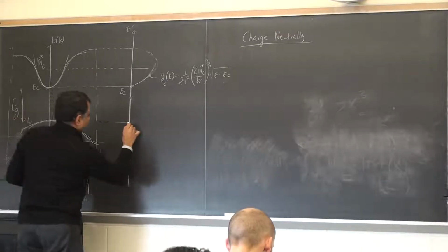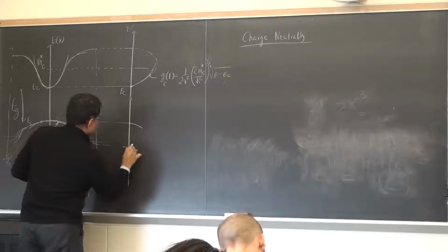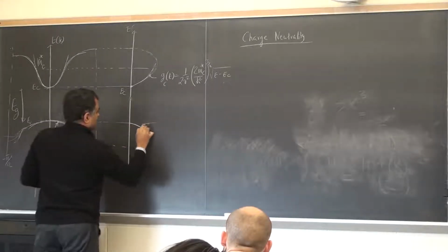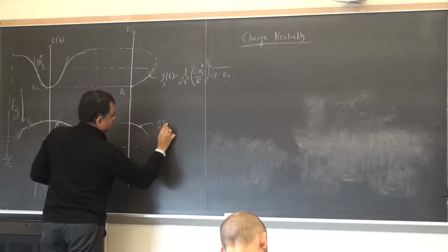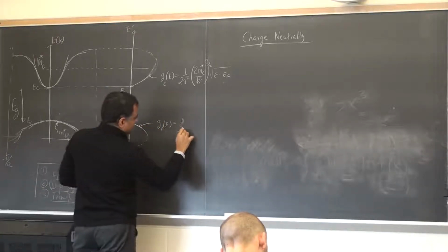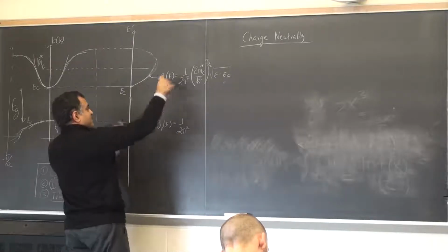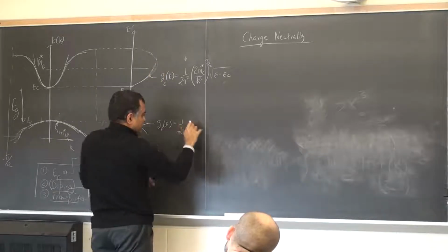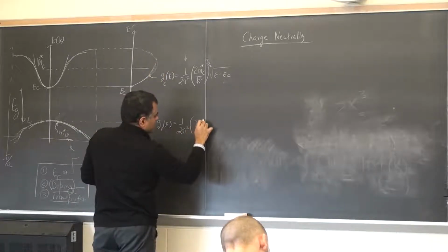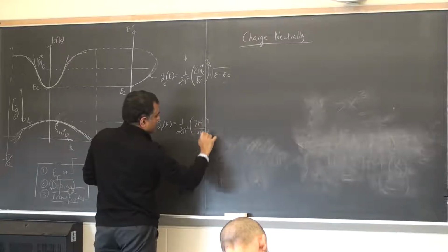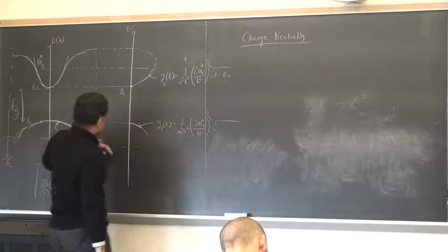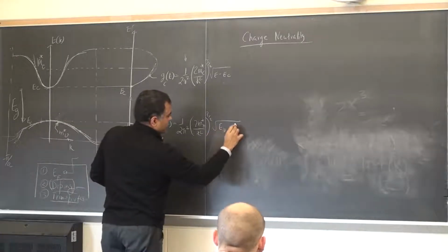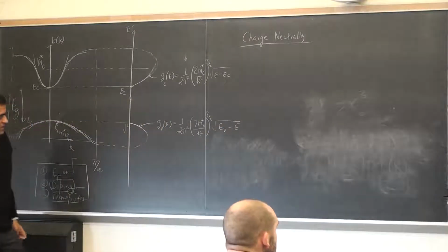And exactly in the same way, the valence band will also increase as square root, but then it will also kind of go down. And let me write that down. Valence band density of states is, again, like 1/2 pi squared. Generally, there'll be valley degeneracy here if you have multiple valleys. I'm saying this, let's just look at one valley at this point. Mass of the valence band over h bar squared, to the 3/2, square root. And now you have to kind of, you know, excess energy is downwards, so you get EV minus E. That's just to be accurate.